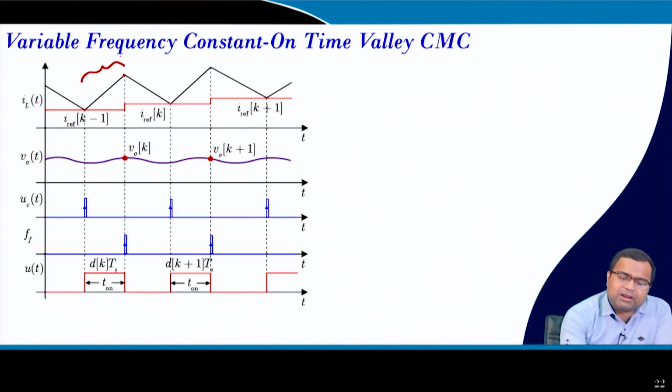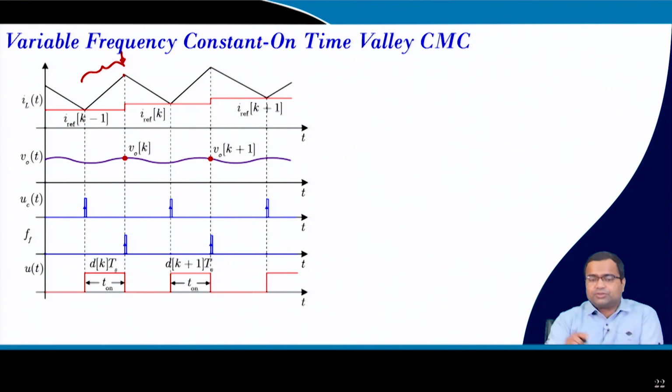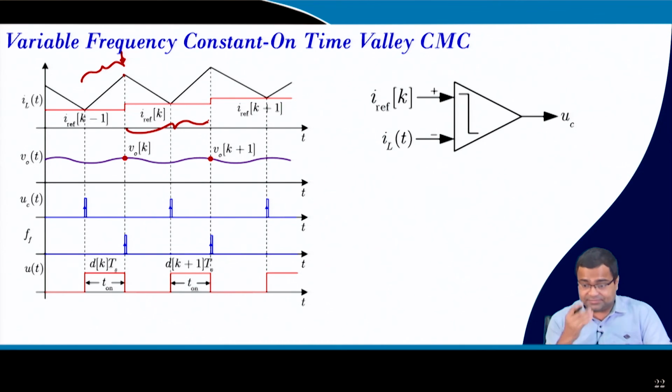Once the timer almost finishes the timing, you send a sampling command, and after a short time you turn off the switch. That sample takes the valley current, and then you can do the regular valley current operation, so the valley current remains fixed for the whole duration. Again it is event based sampling, one sample per cycle, and you can stabilize and get a wide operating range.